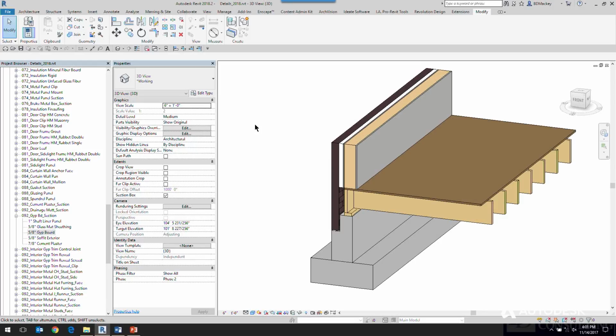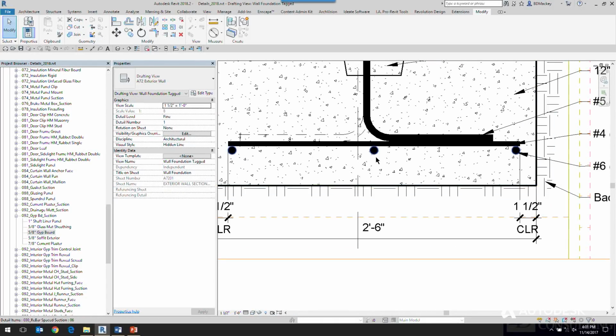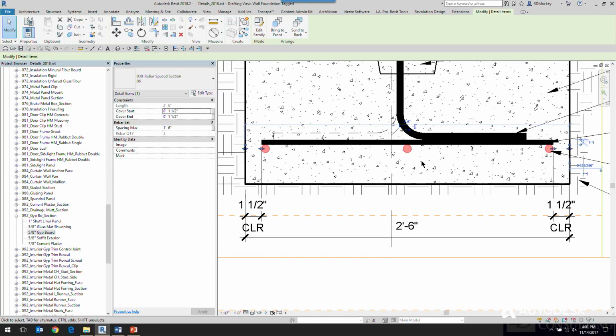The other thing on that is, if I go back into this view here, I also like to, for my structural engineers in the room, start embedding a little bit more information. I like to create a lot of detail components that automatically have an array in them. Because anybody here use a repeating detail component in Revit? It's a really great tool, but you can't tag it, you can't keynote it. You can't tab select to get to the detail component to tag that or keynote that, okay?